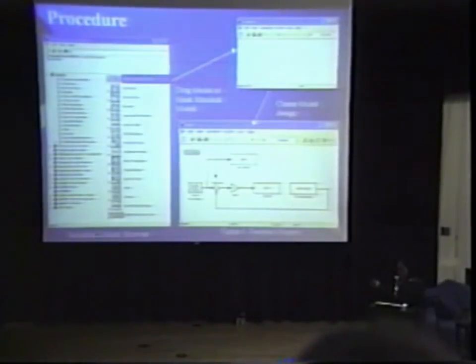The set point block subtracts the amplitude of 0, which then goes into the gain block, making the voltage of the motor that of whatever the gain is set, in this case 2, with a period of 2 seconds. It is important in this system not to exceed the gain of more than 4 or 5. The difference can be heard in the motor. The position of the gear goes from 0 to the set value every 2 seconds.